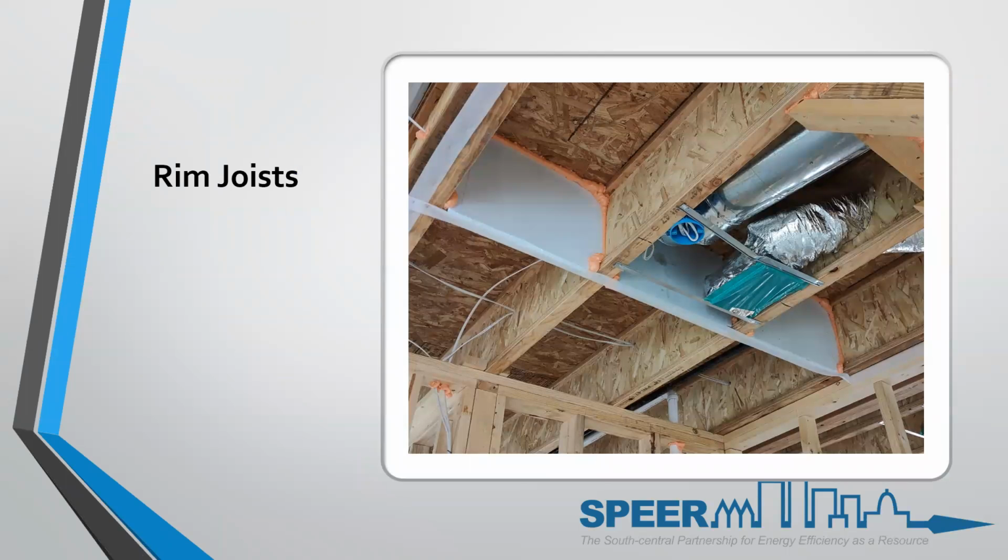If it doesn't exist, like if the band joist isn't created by framing or isn't as easily identifiable as over a garage wall, it must be identified where the stopping and starting point of the upstairs conditioned room ends and starts, or attic starts. Then basically you need to create it below that, and those spaces between in that subfloor must also be blocked. This is over a garage, and the blue insulated board or continuous foam board is creating a band joist.